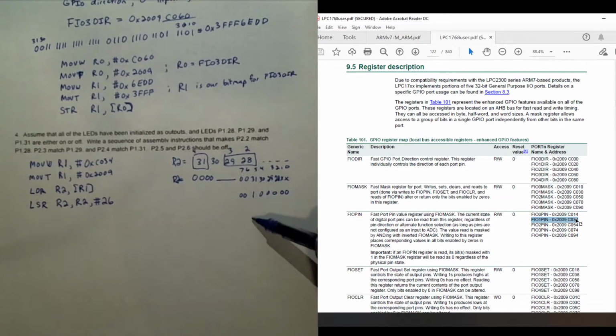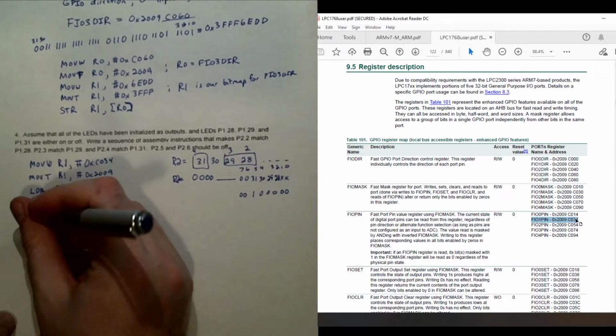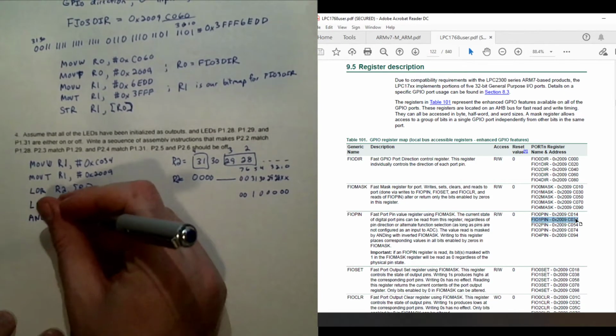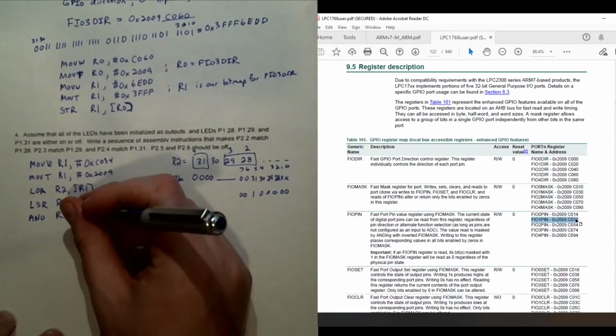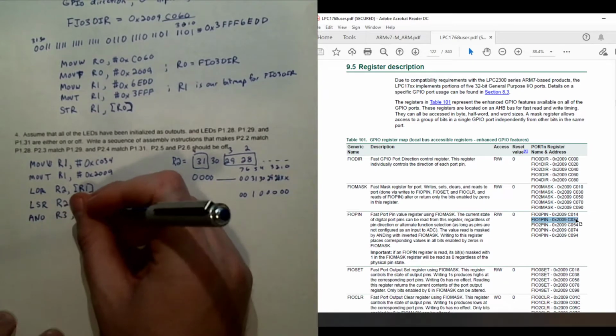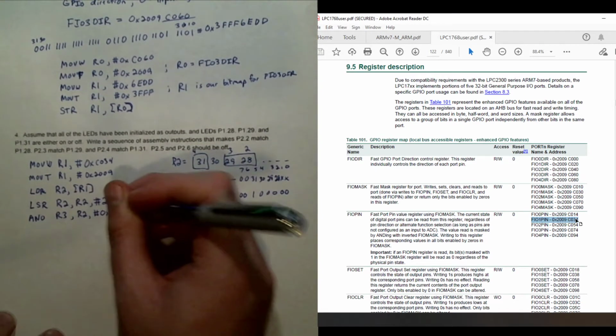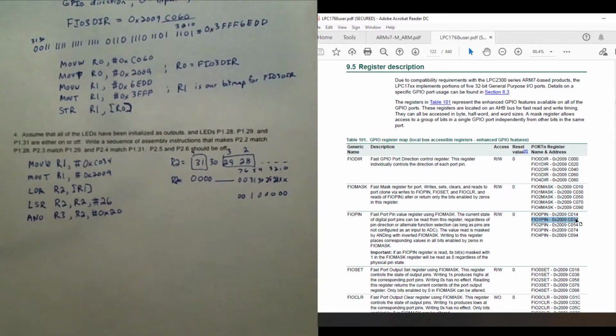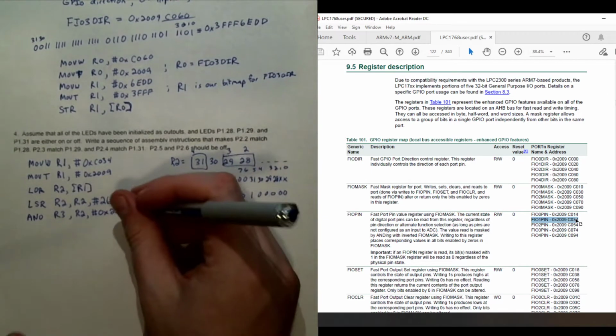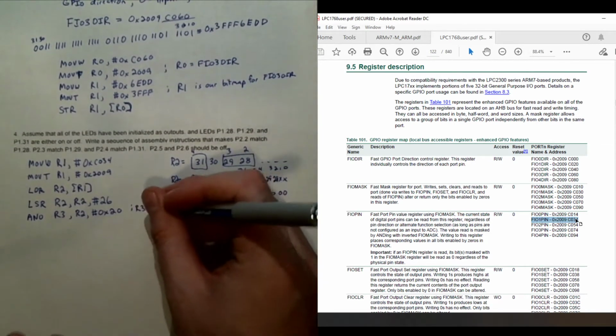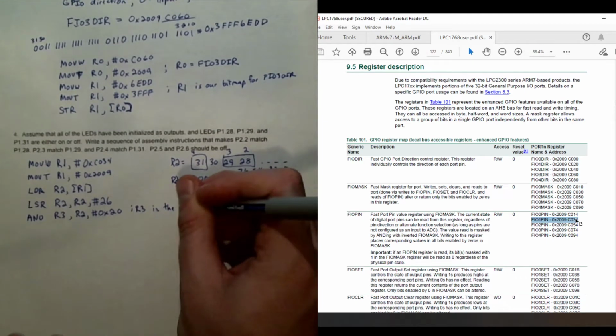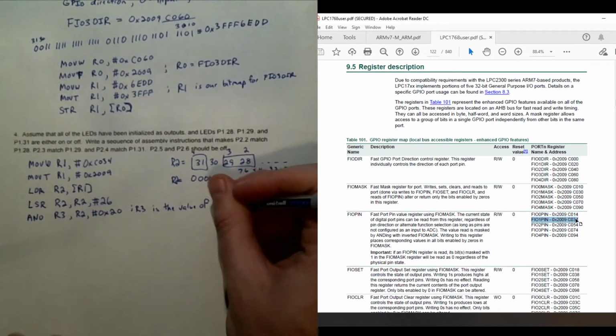So if it's a 1, it'll stay a 1. If it's 0, it'll stay a 0. And if it's a 0, we're doing some extra work here, but it's okay because we want this to be general so that it works whether it's a 1 or a 0. So I'm going to AND into register R3 from register R2 with 0x20.